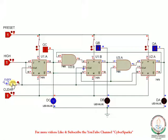So likewise, you have to analyze the flip-flop inputs J and K before giving each clock pulse and correspondingly observe the output. On the second clock pulse the output becomes 010. At the end of the third clock pulse the output becomes 011. At the end of the fourth clock pulse the output becomes 100. At the end of the fifth clock pulse the output becomes 101, which is the last state of the counter.